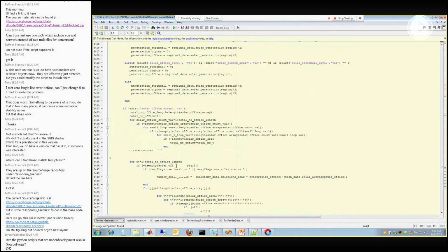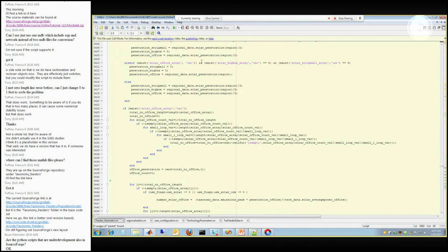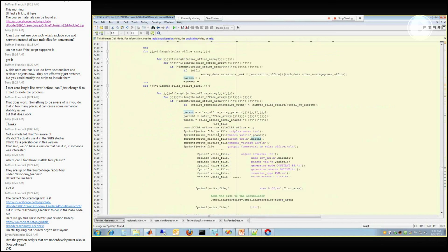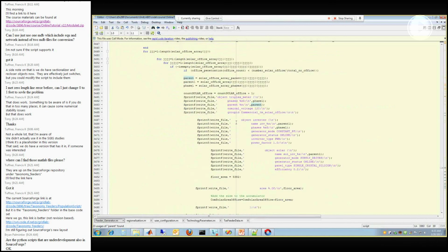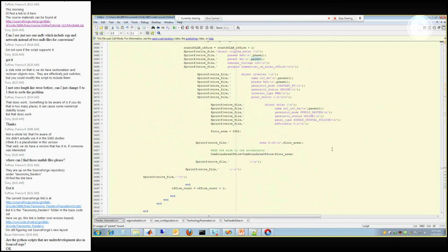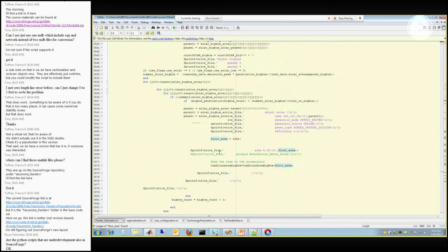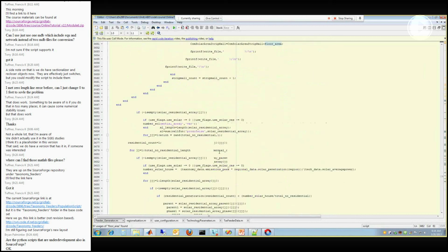So this is really doing a lot of things. Really, it's just trying to decide how many solar panels to populate in each location, depending on your penetration levels. Once it does that, it actually populates the new triplex meter, an inverter, a solar panel, and things like that, and determines what size to put onto it. In this case, you can see it's a hard-coded area, but you could adjust that to whatever you'd like. It does the same thing with the commercial buildings.